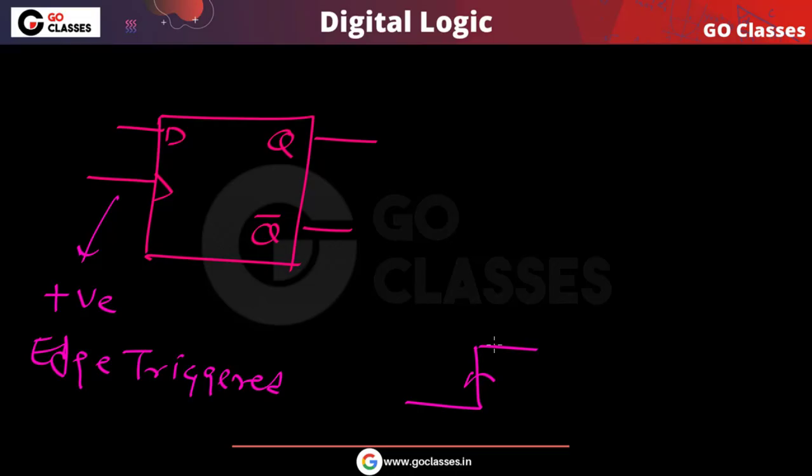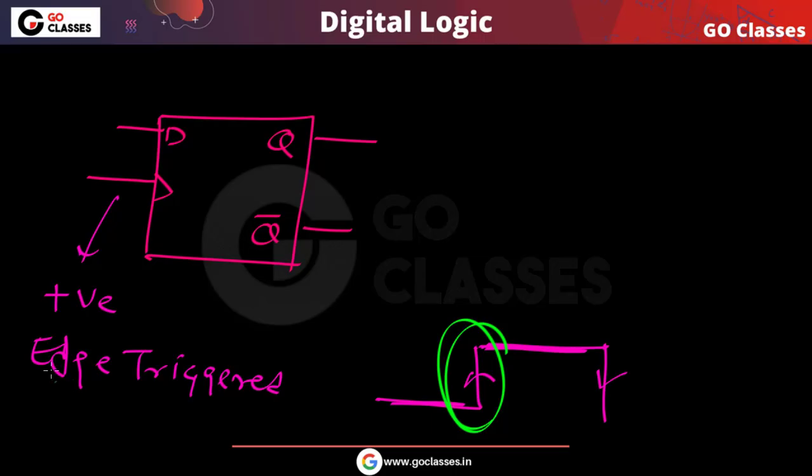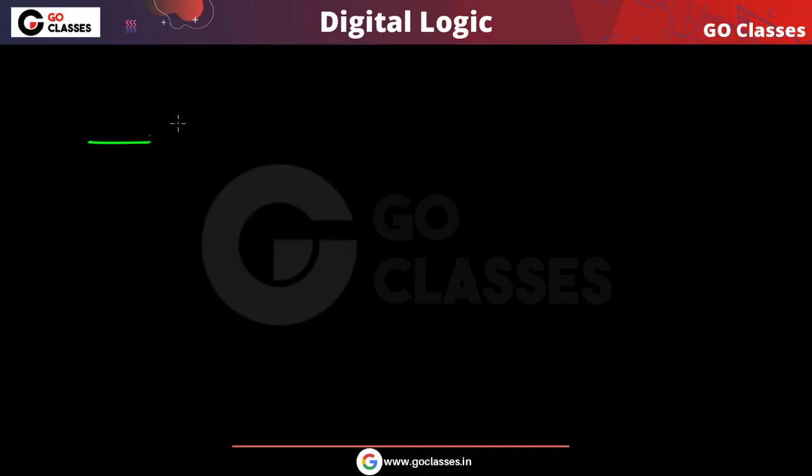In the remaining time, for example when your clock is 1, when your clock is 0, or when your clock is falling, this flip-flop will not work. Only during this rising edge, this positive edge, this flip-flop will work. Now let us see what the issue is here. Let us assume this is your clock.